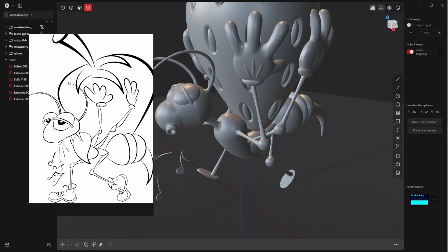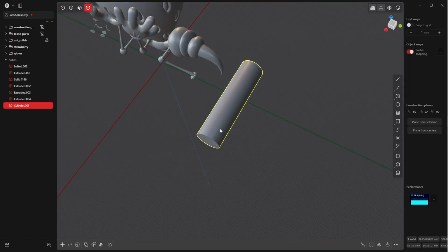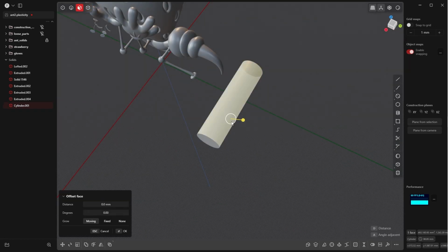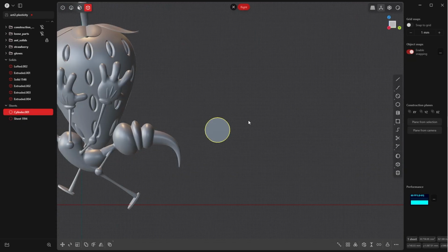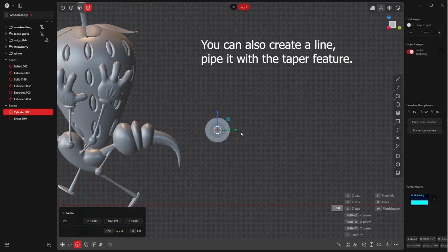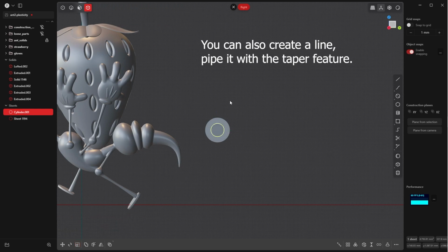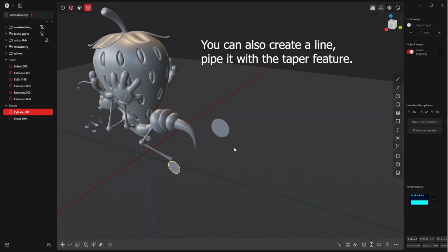We can even put these things, these guys. So let's create a cylinder like so. Go to face mode, select the face, delete it, go to solid mode, right view. Maybe I'm doing too much complicated stuff and there are far easier ways.